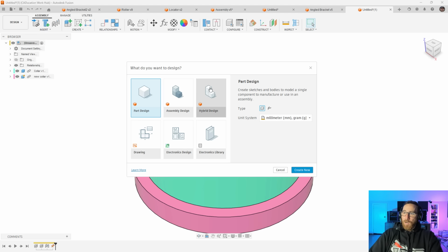So as you're getting started, the first thing that you want to understand is have a picture of your design. Are you creating a part? Typically a part that was external was meant to be used in multiple assemblies. In this case, that's not really the default definition. What this means is you're designing a single body part, a single body component in Fusion speak, and that's going to get inserted into an assembly. Now, it doesn't have to be. I'll show you an example of multiple bodies in a single part, but that is the default rule that we want to follow.